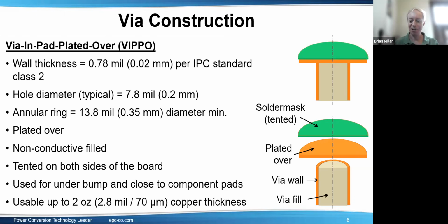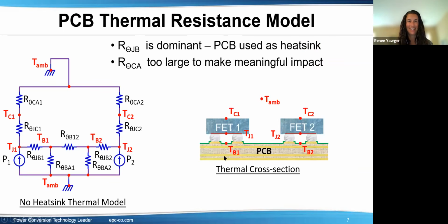That's a good mystery. If it didn't heat up at first and conducted 15 amps, that's a real good sign, because there's not much thermal mass in the GaN FET. So the fact you have 15 amps flowing through it, and you put your finger or other device on the FET and it doesn't seem like it gets that hot, that's good, because it means it can take that.